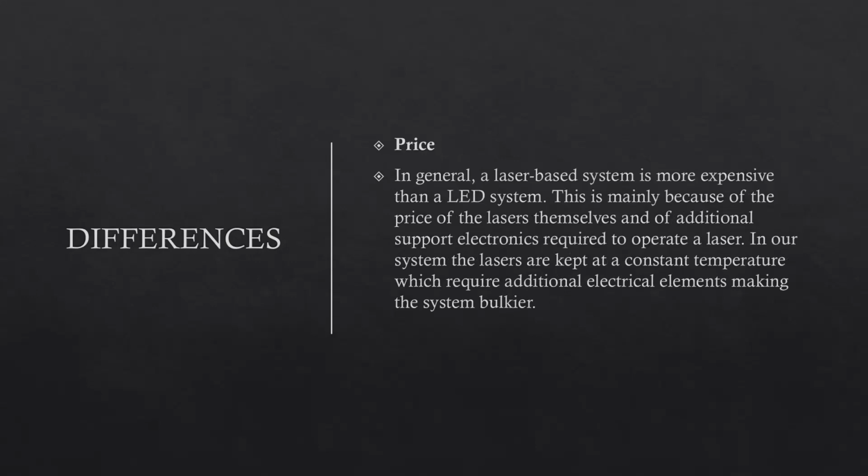In general, a laser-based system is more expensive than an LED system. This is mainly because of the price of the lasers themselves and of additional support electronics required to operate a laser. In our system, the lasers are kept at a constant temperature, which requires additional electrical elements, making the system bulkier.